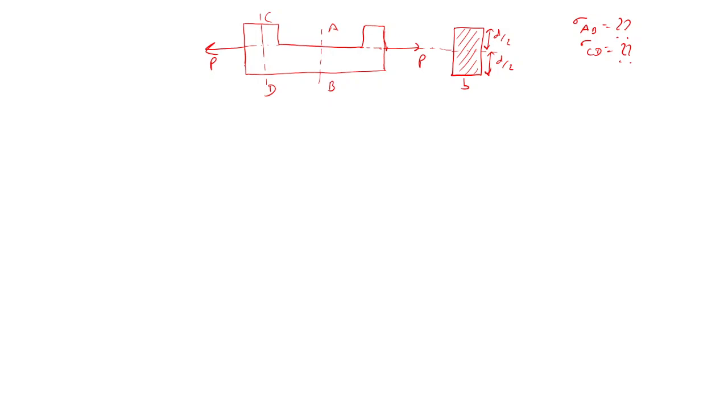Anyone solved? Yes, sir. I have solved, and I am getting the overall bending stress at the bottom in section AB as 8P upon BD. Total stress or only sigma b? Sir, overall, bending plus this tensile. Okay. Tensile will be 2P upon BD. Okay, total you are getting 8P by BD, right? Yes, yes. Okay. So the remaining can solve for 1 or 2 minutes, then we'll start.